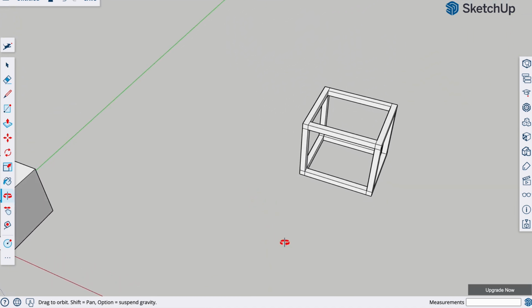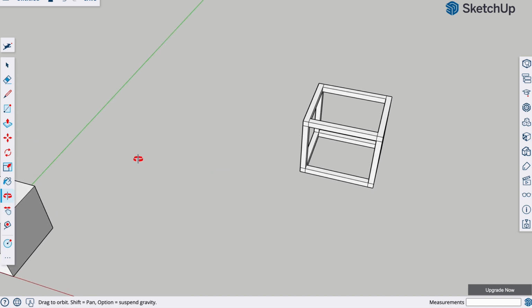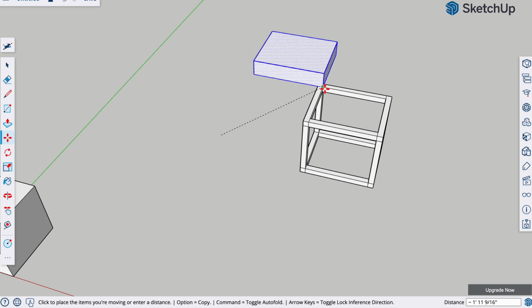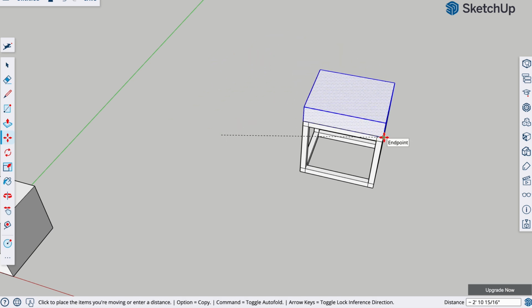And if you want to make it a little more realistic, sometimes what I like to do is hit T, see how long this was. 14 inches by 12 inches. So what you could do is come over here and do a 14 inches, that's feet, by 12-inch rectangle, hit P. Let's say we're going to have a 3-inch cushion, so we're going to drag it up 3 inches. And, okay, so theoretically, we want to drag this here, which is a cushion, right? But as soon as we do that, I'll show you.